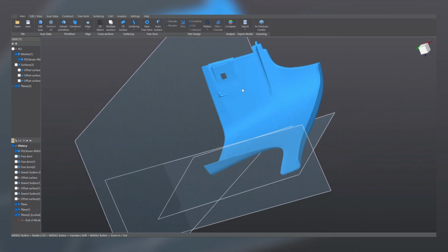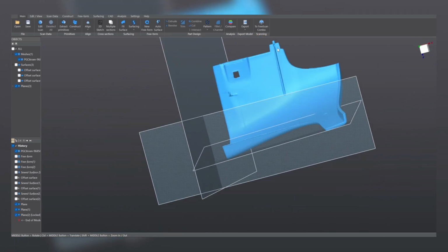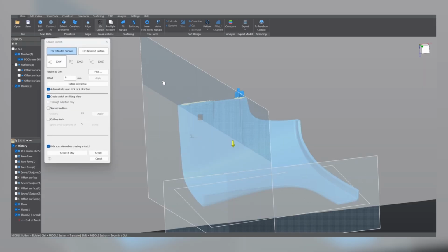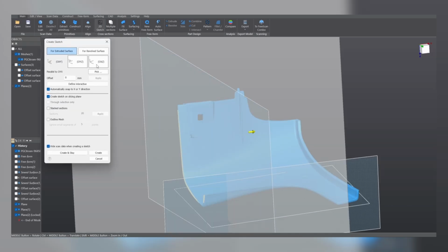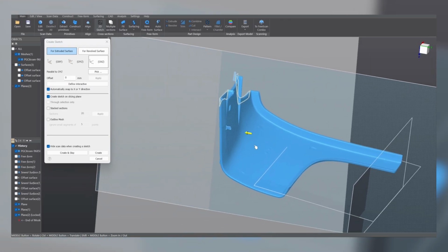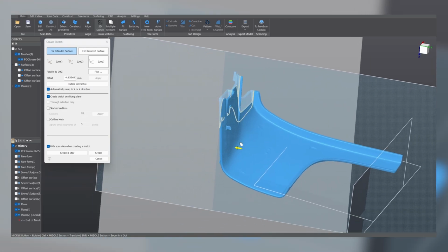Cool. Now, for this geometry here, the way to approach it is by extruding a sketch, an open sketch, to obtain a surface. So let's do it. Click onto this sketch, select the proper orientation, and the first thing that we observe is that when moving this plane, we are not able to slice on the position that would work well for us to extract this information, right?